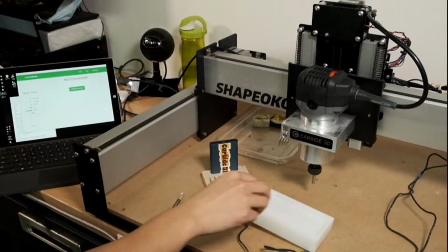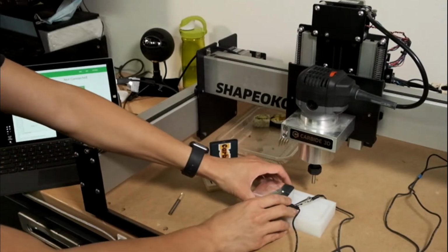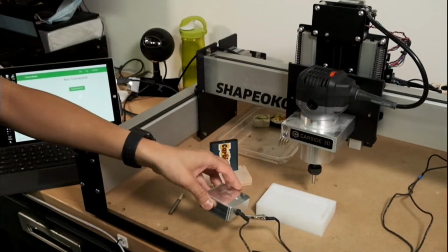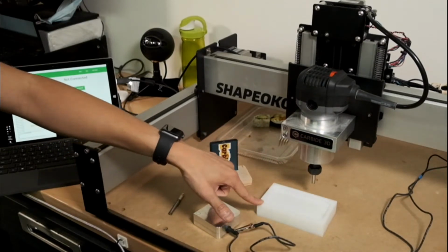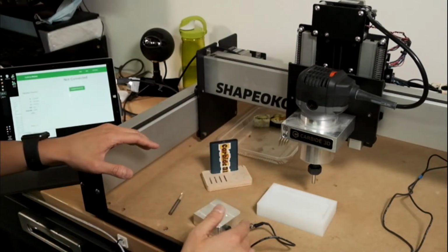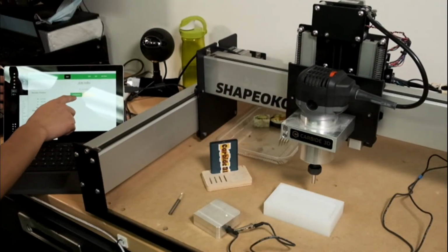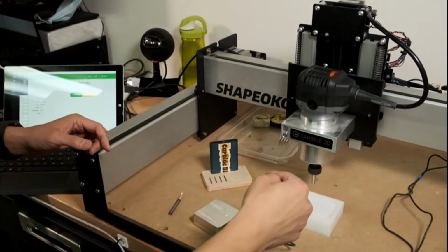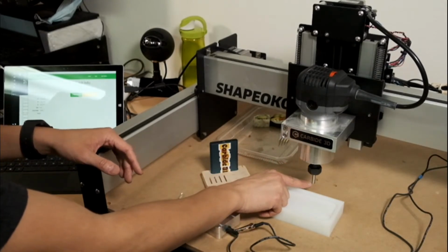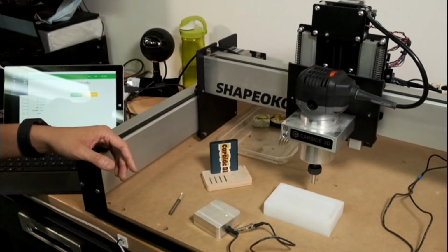Okay, so to recap, BitZero finds your origin the first time, and should you lose that reference point, like if you machine away that corner, the BitSetter will adjust for the Z height every single time you change a tool, and you don't need to worry about X and Y. You only ever need to find X and Y the first time, because after that point the machine will remember the X and Y coordinate. That part never changes. So the only part, once you start machining, that will change when you change a tool is the Z height. So that's why you have the BitSetter to adjust for that.